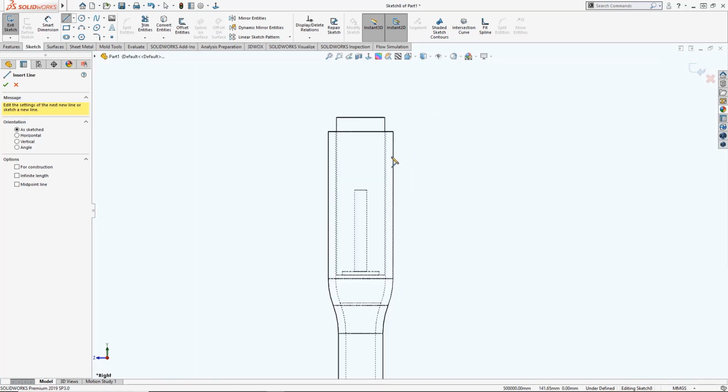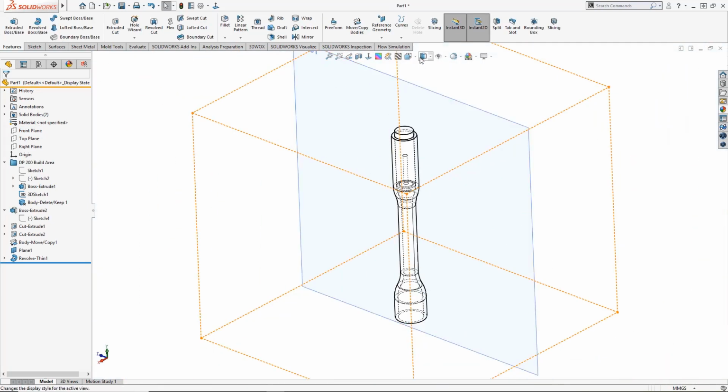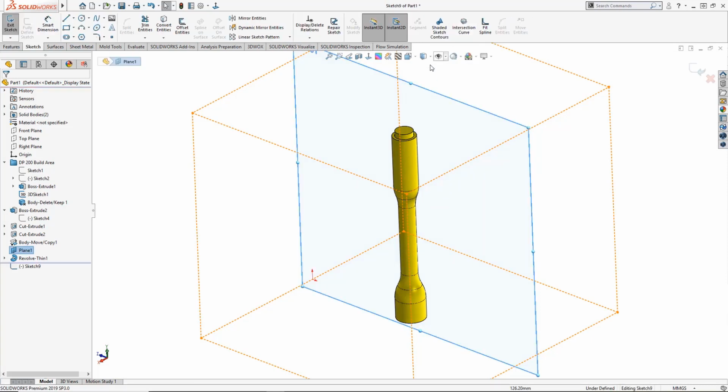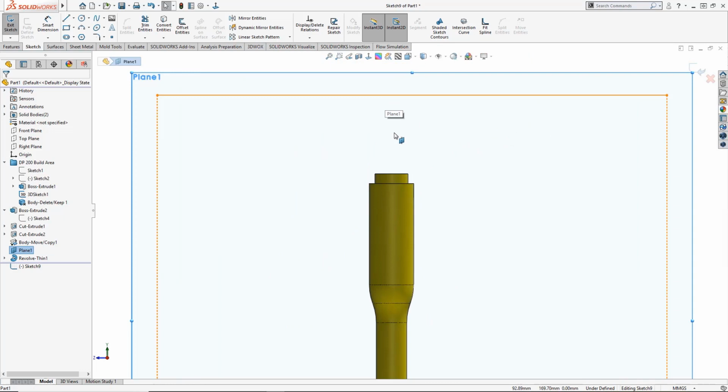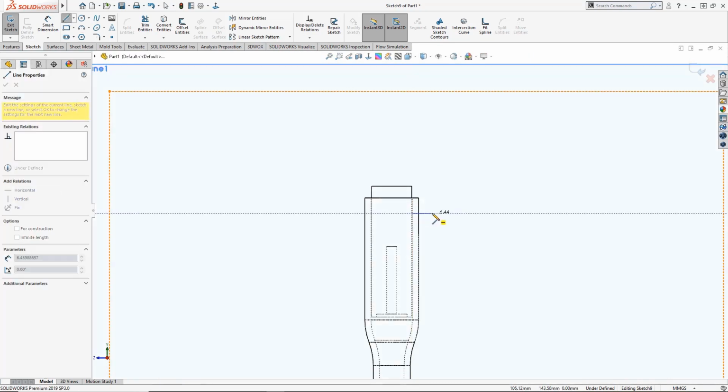The fins themselves, I want to go ahead and reference the inside of the motor, because it's the inside of the cavity actually. In this particular case, I want to reference those edges because when I extrude my fins straight out, if I was to put those referencing the outside edges, they would literally be tangent. And what that would create is a zero thickness geometry condition between that outside edge and my fin. So here we're going to go ahead and snap to the inside edge.